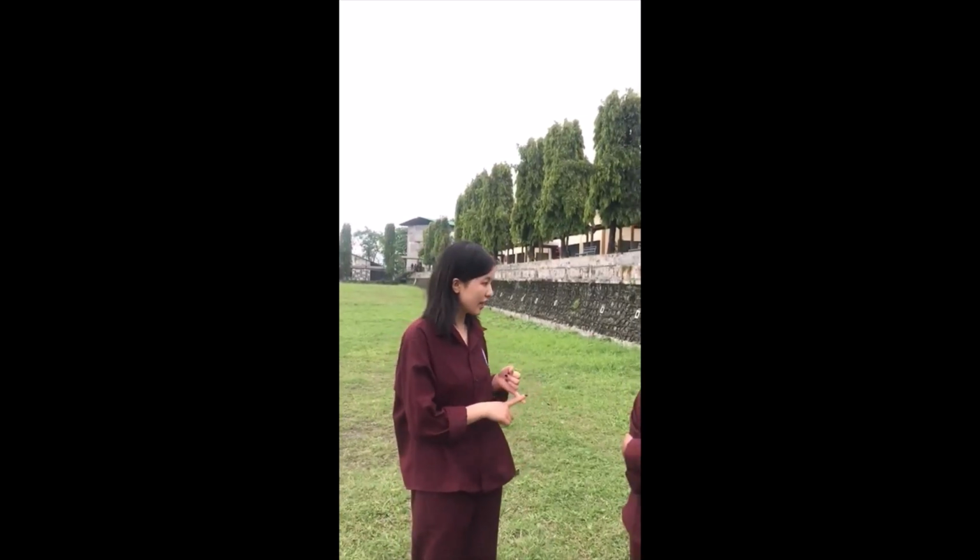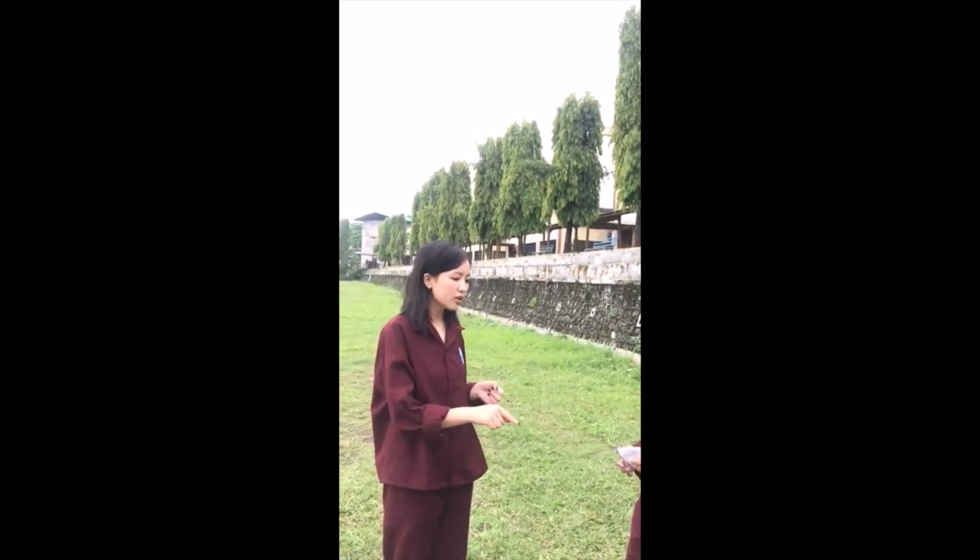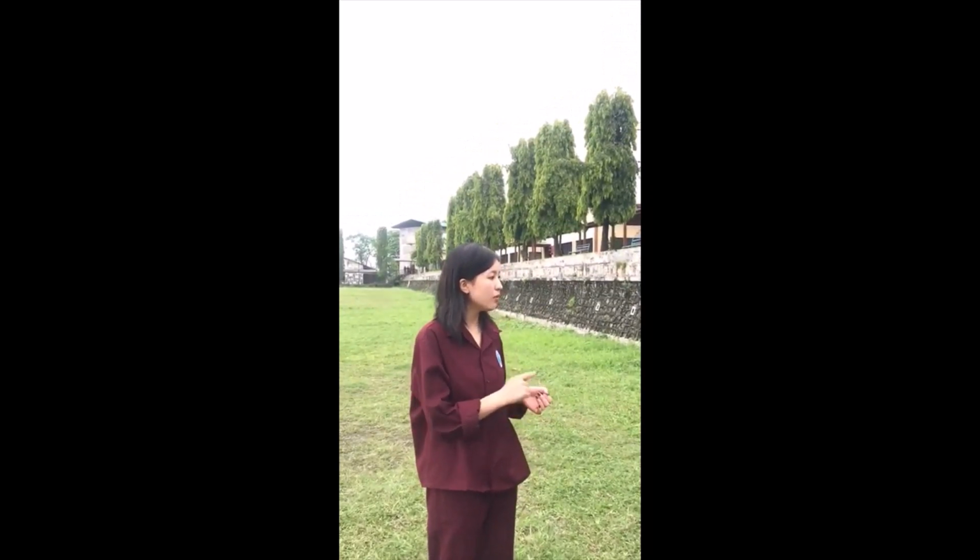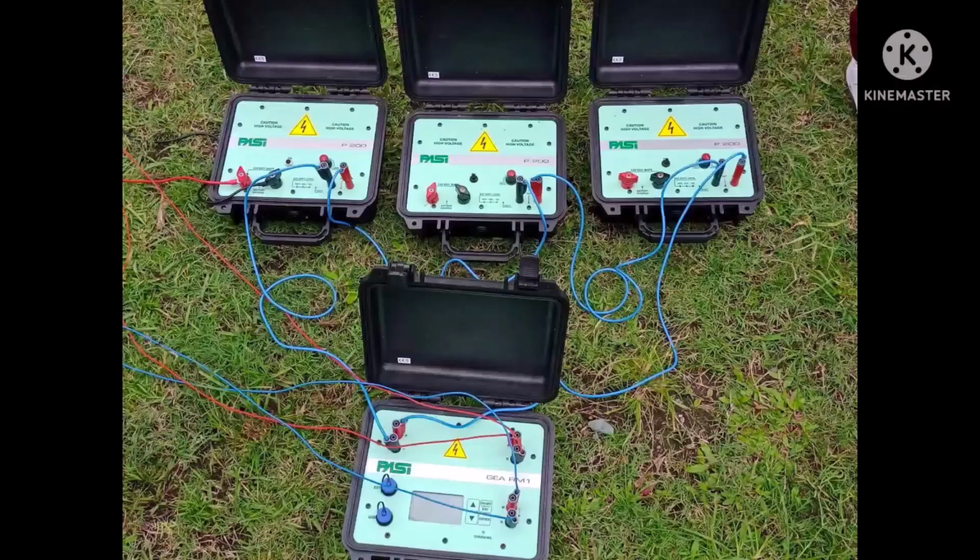So in ERT, the known amount of current is transferred into the ground with the help of current electrode, and correspondingly the voltage from the ground is measured with the help of voltage electrode. Current and voltage measured gives us the value of resistance, which is multiplied with the error factor K to get the resistivity. So now with the help of softwares, the resistivity value obtained can be used to get the ERT profile. Sherab, if you could explain me about the setup, data analysis and computation.